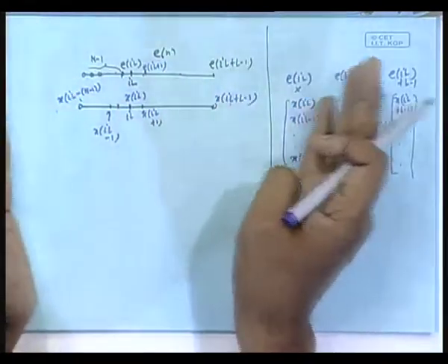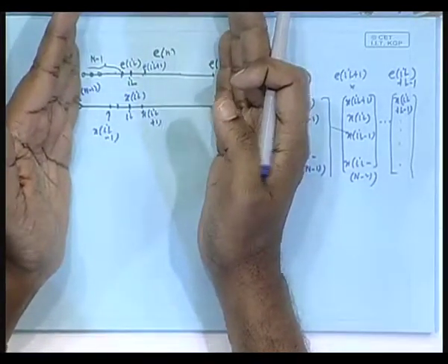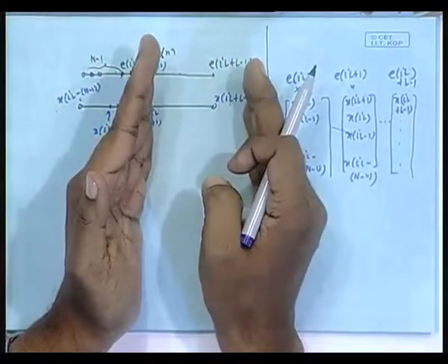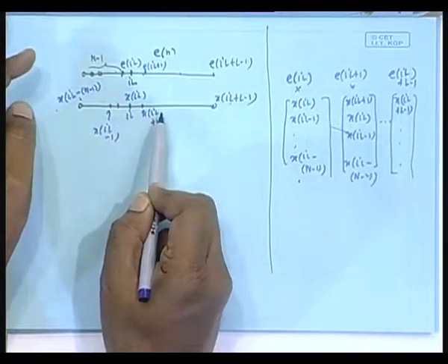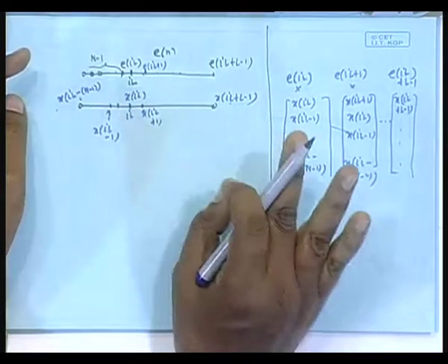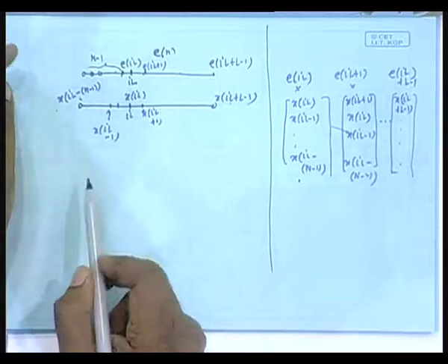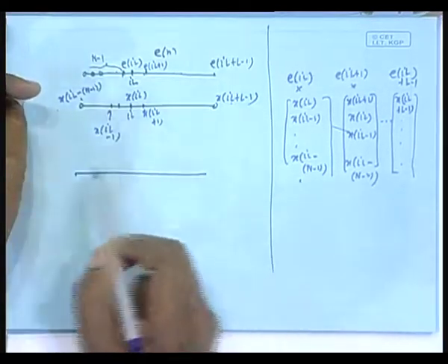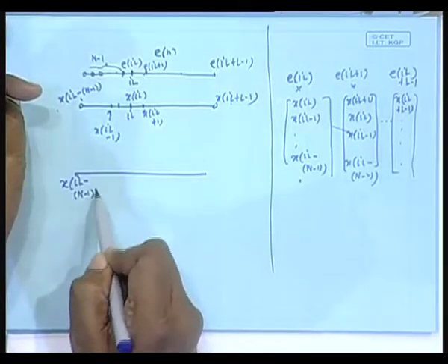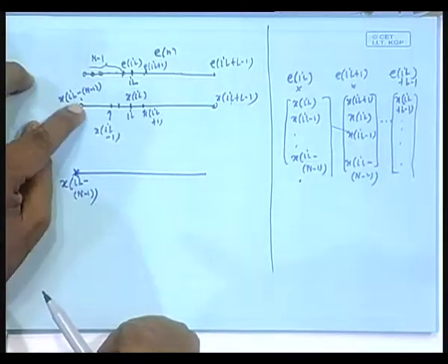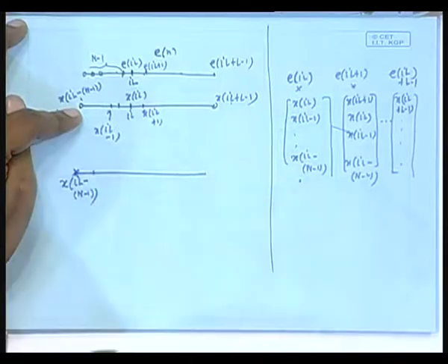That is, make a periodic version, reverse it, then without shift, whatever you see in the window, multiply, you get the first entry, then shift it once. In circular convolution, you go on shifting even beyond the n minus 1 shifts, because you have to complete the entire thing, but I will ignore those results, I do not need them. All right. That means, originally what is the sequence? X, here, this as it is. Can you tell me, if you reverse it, what will be before this?